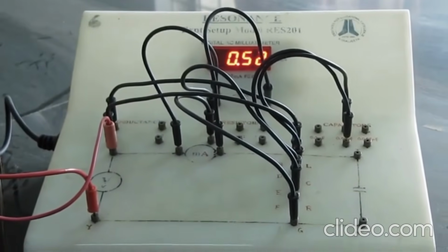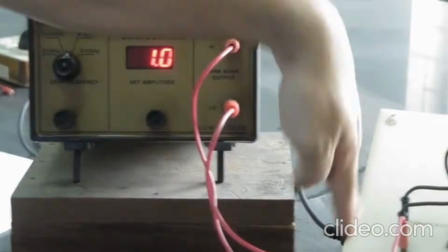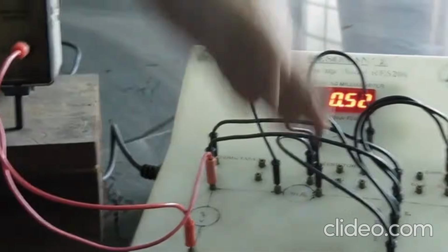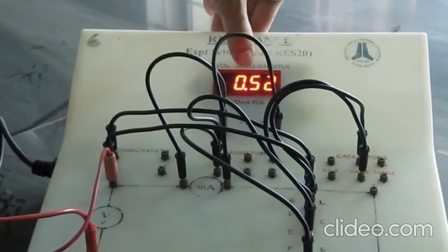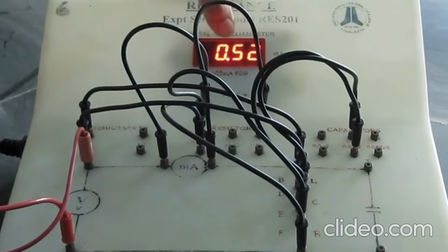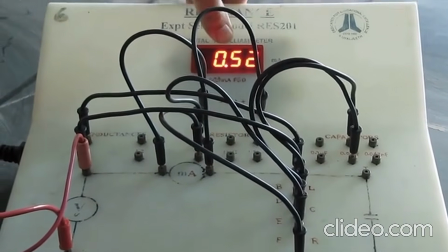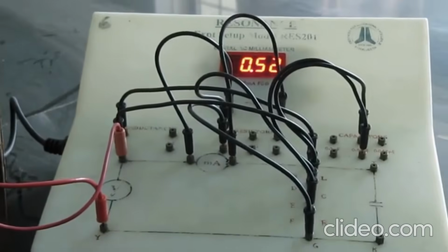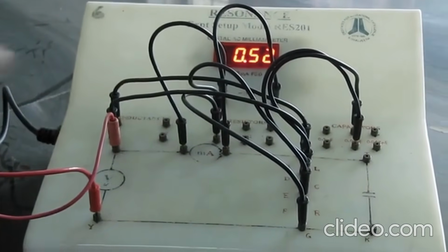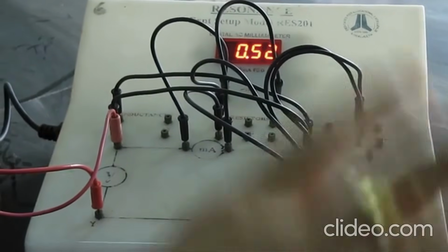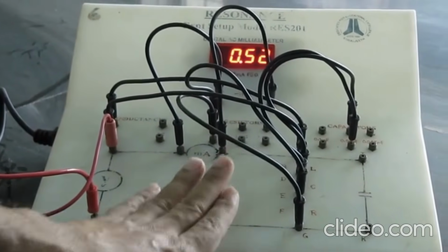The circuitry is not that difficult; once you go through it, you will be able to understand it pretty quickly. Now what I am going to do is change the frequency of the AC signal that you will put in that input terminal, and I will try to record the current through a milliammeter. You have a milliammeter there. Whatever you see in this panel is the current in milliamp. Change the frequency, record the current, and then you plot it, and then you perform some mathematical steps, and finally you will be able to find the answers of all 4 or 5 parameters that you want to find out.